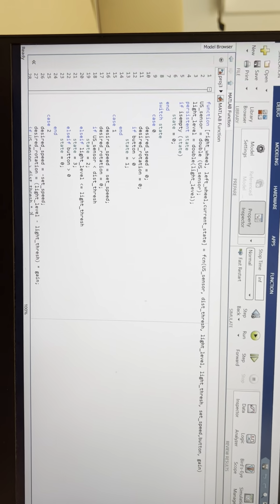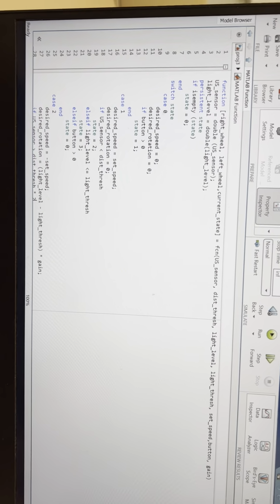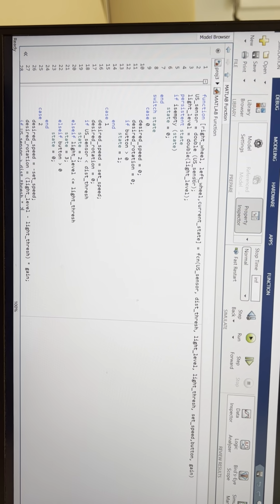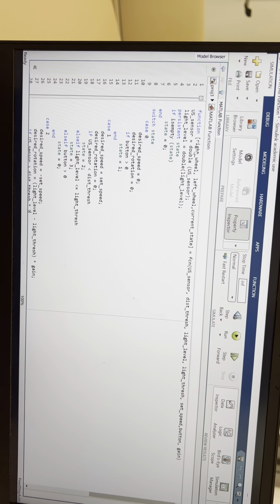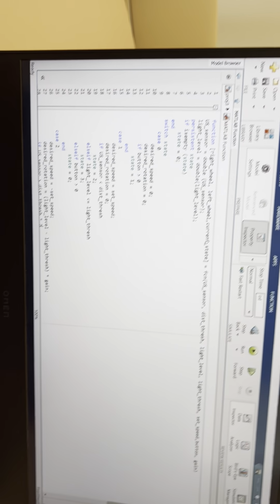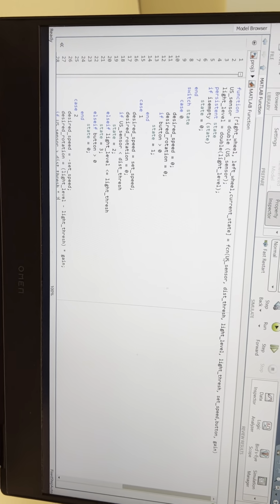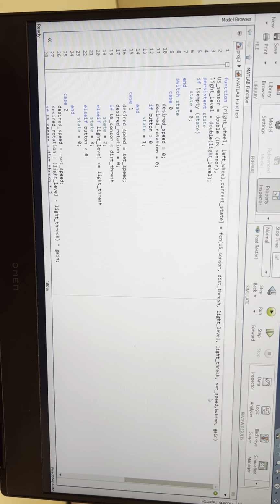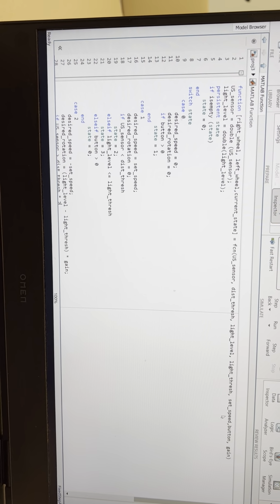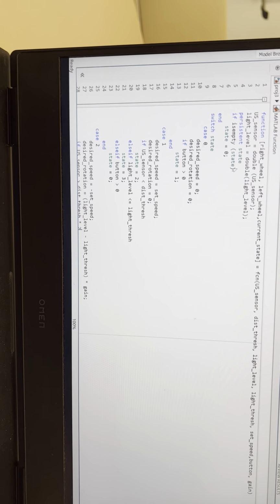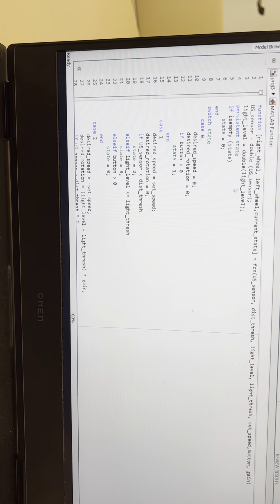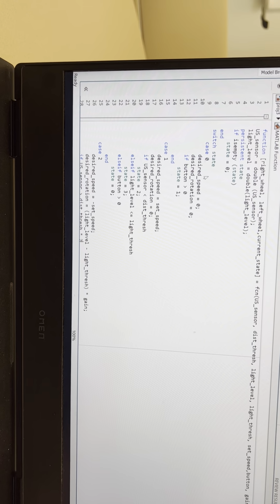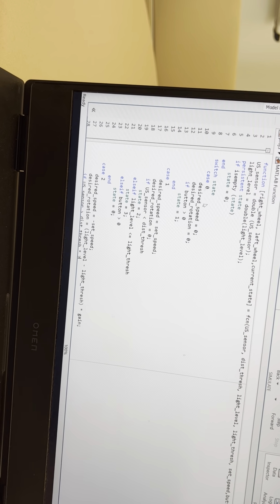Okay, so this is our function. This is like the brain of the robot. Our outputs would be right wheel, left wheel, and current state. They go to the right motor, left motor, and the display on the robot. The inputs will be the ultrasonic sensor, a distance threshold, a light level, a light threshold, a set speed that we already put out, the button, and the gain. We decided to double the value of our ultrasonic sensor and color sensor. This is basically dividing that, saying that our robot has 3 states.